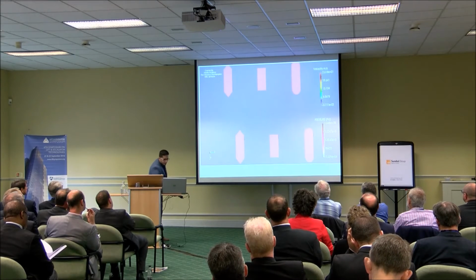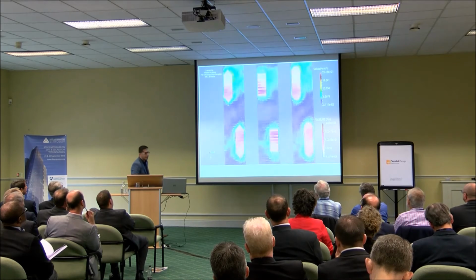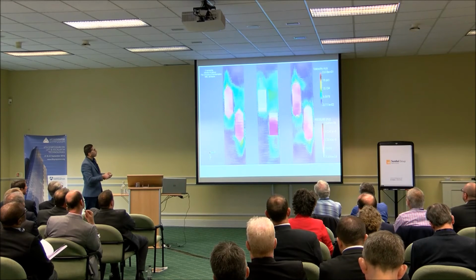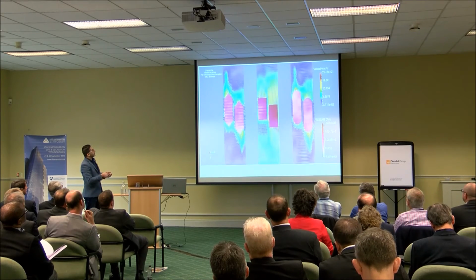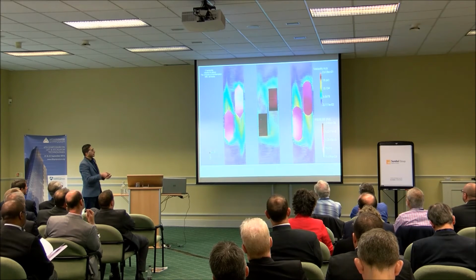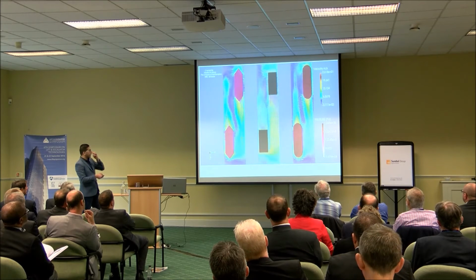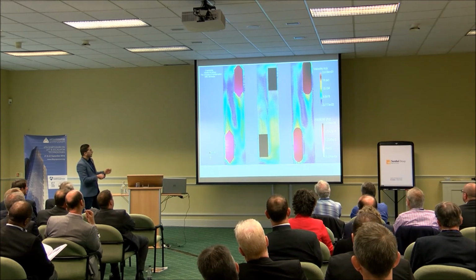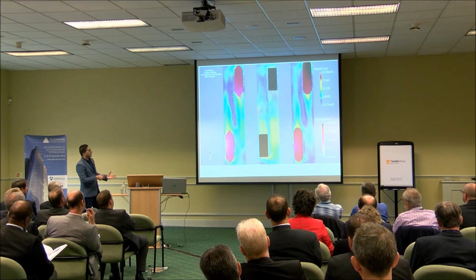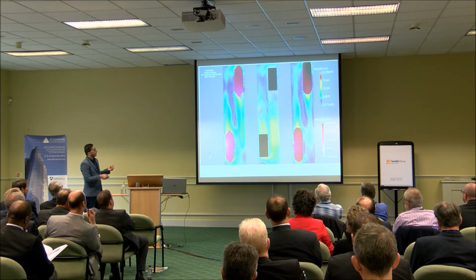Okay, this animation shows the air velocity vectors in the hoistway, and also it shows the pressure distribution values over the cars' bodies, and you can see clearly that the pressure that acts on the triangular lift is again less than the pressure magnitude that acts on the other lifts.